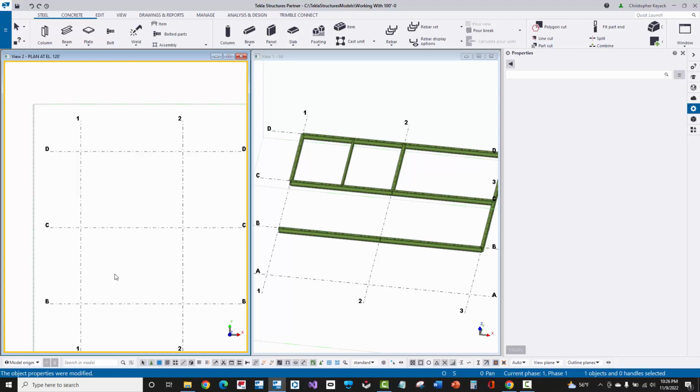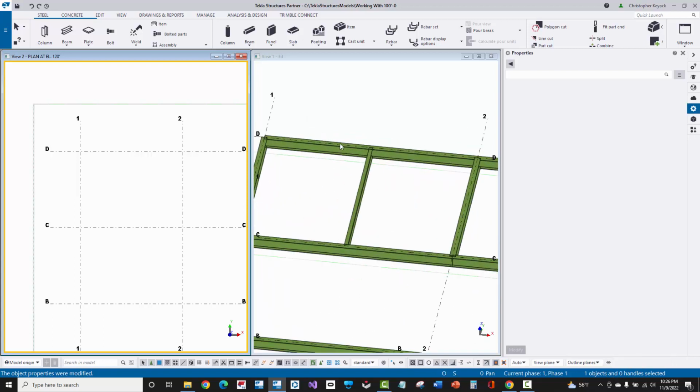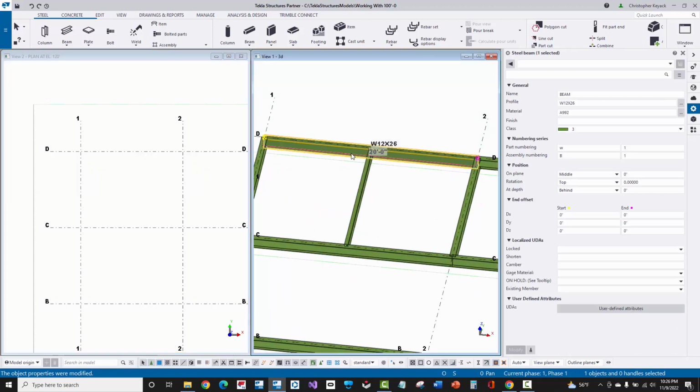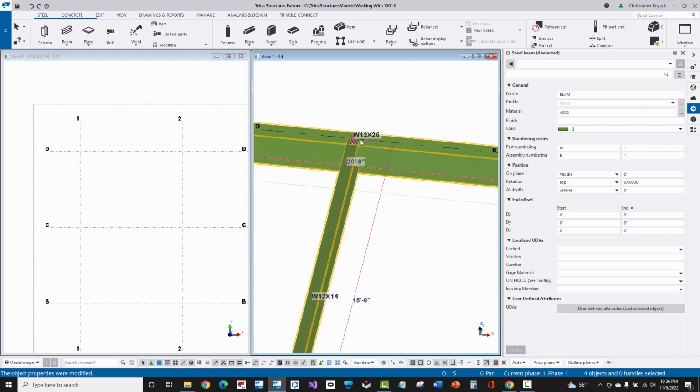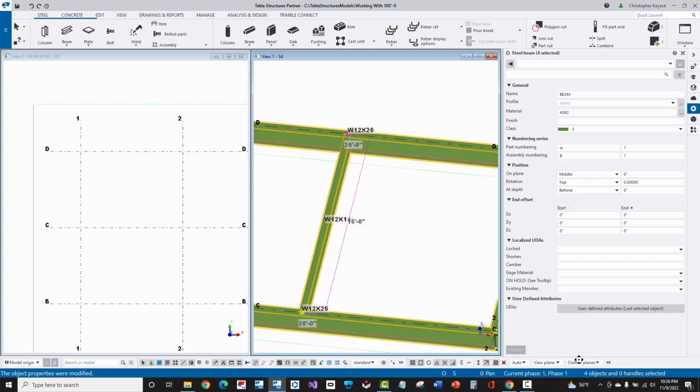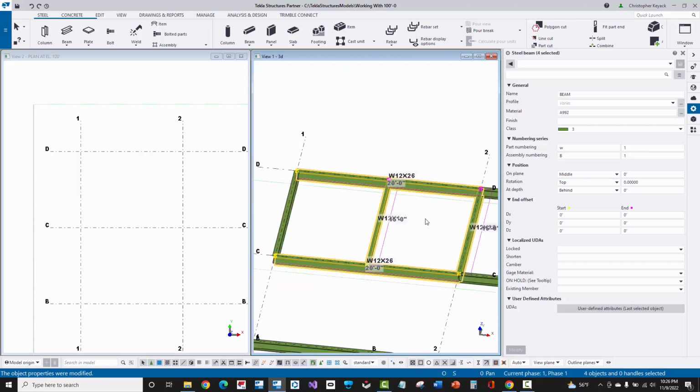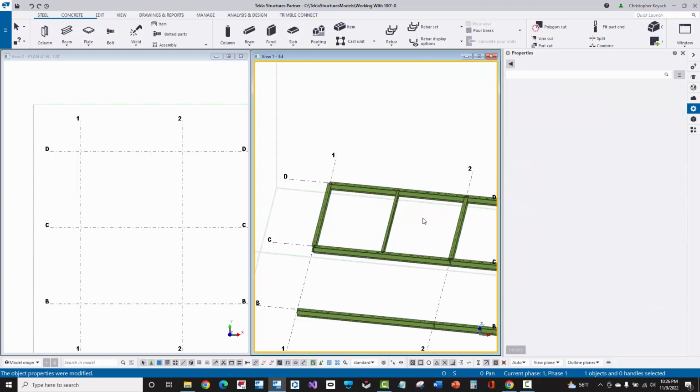One last thing that's pretty important is that in the lower right-hand corner, there's some different information. The most important thing I would say is the ability to see the number of objects that you have selected. If I click on a piece, you'll see that it's highlighted, and at the lower right-hand corner it shows that there is one object selected. If I hold down Control, that allows me to add to my selection set, and now I have 4 objects selected. This comes in really handy to verify if selection filters have found anything that you can't easily see, especially if it's small and you're zoomed out on the model. So selection filters and this quantity of objects selected can be pretty important.